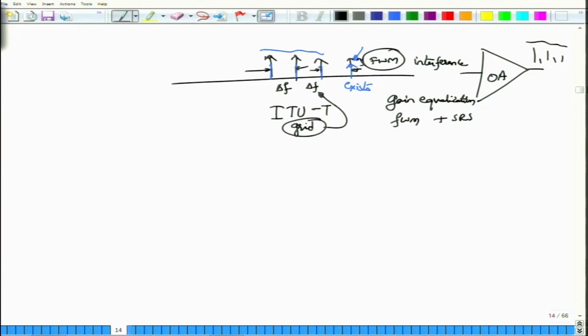So, as I said, we are done with nonlinear effects, and as I have told you, nonlinear phase noise will affect the phase modulated systems. FWM effect will affect everything. It will add extra noise in the form of additive Gaussian noise. It may or may not be white, but we usually make that assumption to be clear about that one. Okay, we have talked about optical fiber properties, right.